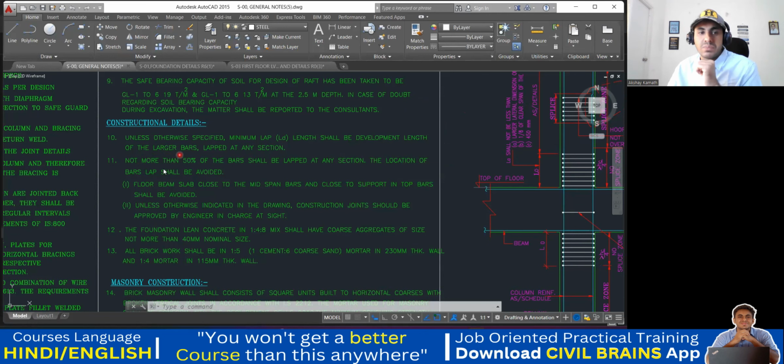So that is what they are trying to tell us, that it shall be the development length of the larger bar. Not more than 50% of the bars shall be lapped at any section. That means, I told you, whenever you are lapping the bars, you should not lap more than 50% of the bars. If you have 10 rebars, only 5 bars have to be lapped at one section. The remaining 5 bars, you lap at another section. So it's telling not more than 50%.